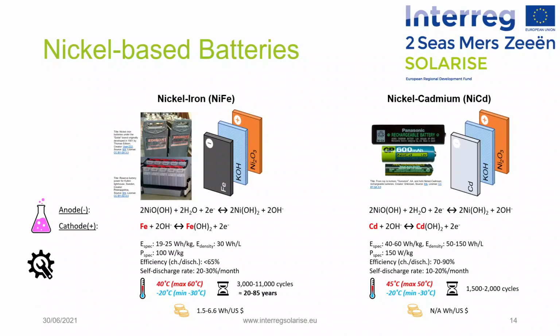The nickel-cadmium battery is also composed of a positive nickel oxide hydroxide plate, but with a negative metallic cadmium plate and the same potassium hydroxide electrolyte. Compared to other types of rechargeable battery, they offer good life and performance at low temperature with average capacity, but the significant advantage is the ability to provide nearly full rated capacity at high discharge rates. They can discharge in 1 hour or less.